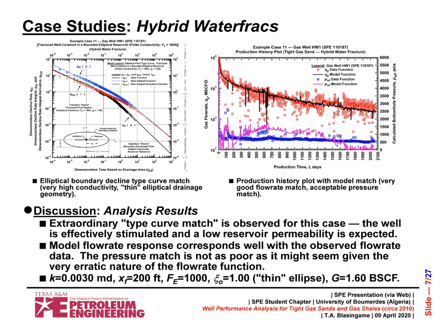The next slide shows a hybrid water frac, which was where people were using a little bit of gel to carry proppant. And I'll go through this one really quickly. An excellent match with the rate function, excellent match with the derivative, excellent match with the integral. Pretty good match with the history match model, fair match on the pressure. This was a low-ish permeability situation, higher fracture half length, fairly high effective conductivity, and then the ellipse is getting smaller and smaller, and a smaller contacted gas in place. So a lot of this has to do with how effective the stimulation is.